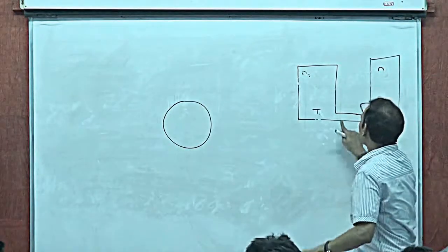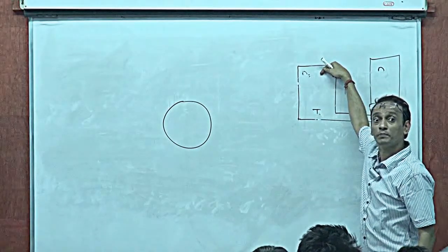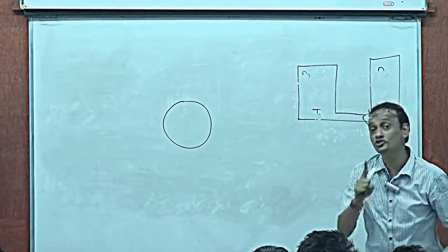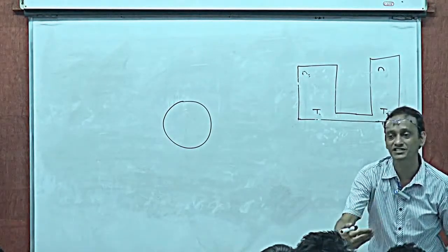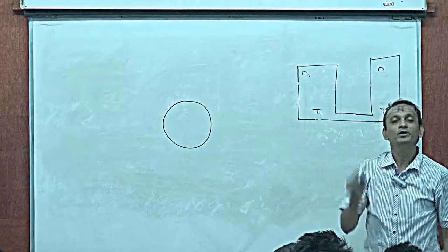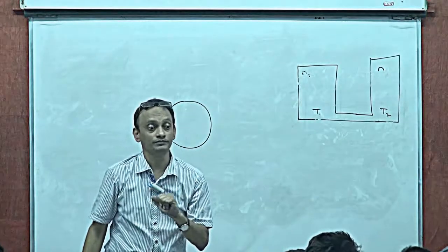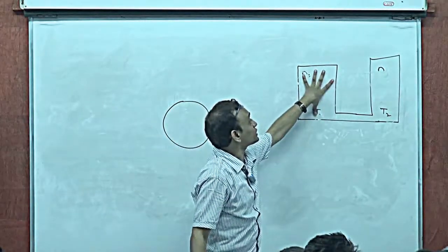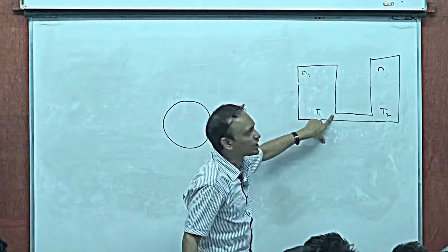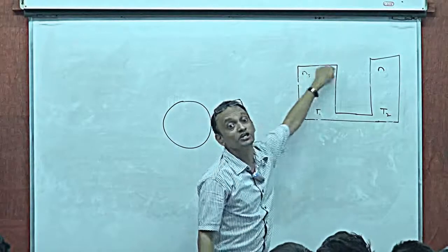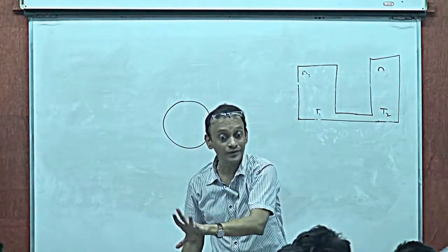If the temperature of this is varying, then at that very instant the temperature of the other parts of the container will become that. It's practical to think, all right, but is not necessarily true. So when can that happen? That can happen if the conductivity of this is infinite, very large conductivity. Any thermal change brought about here at a certain instant is instantly communicated to the rest of the cylinder. That's one case where that could happen, right?